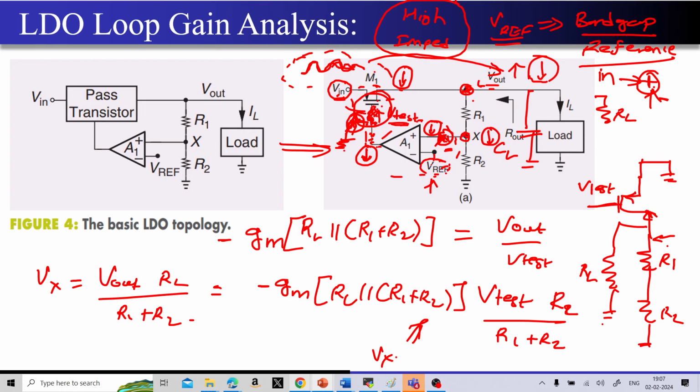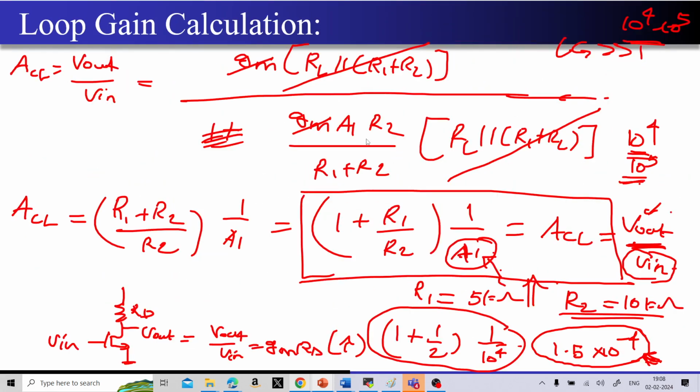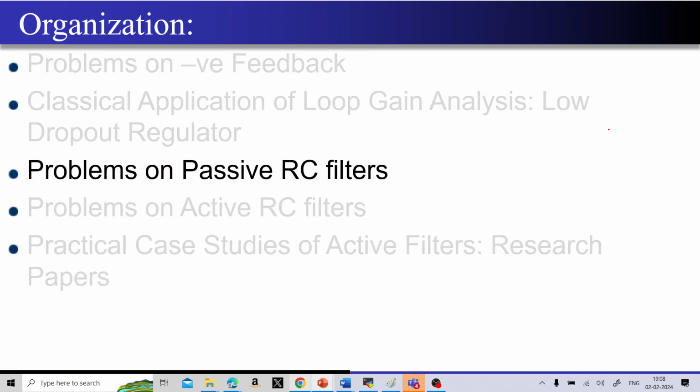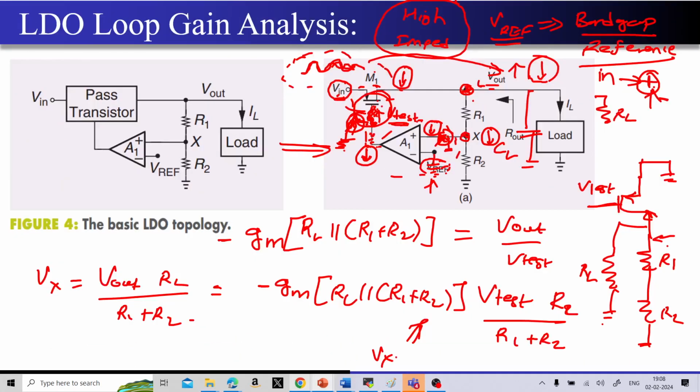The X over here. Okay, this is what you're talking about. So first of all, you have to reduce the Vref over here, and if you just ground this, then what will be coming up over here? Actually, what I am saying is that when you have opened the loop, you have shorted the gate of the PMOS. Yes, the reason why I shorted this is because I don't want any feedback to come over here.